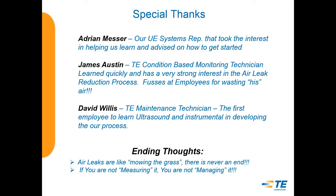Actually, back in our plating process where we do some nickel, gold, and tin plating, all of our compressed air lines back there are PVC. So we do use dope and Teflon together back there. It seems to work a little bit better out in the main manufacturing area. Anywhere where we're using compressed air, we just tried to get away from the Teflon and just use the dope. The Loctite sealant that we use, we almost never see any leaks. If it's put on properly and the fittings are the same and it's snugged up properly, we never see those leaks.